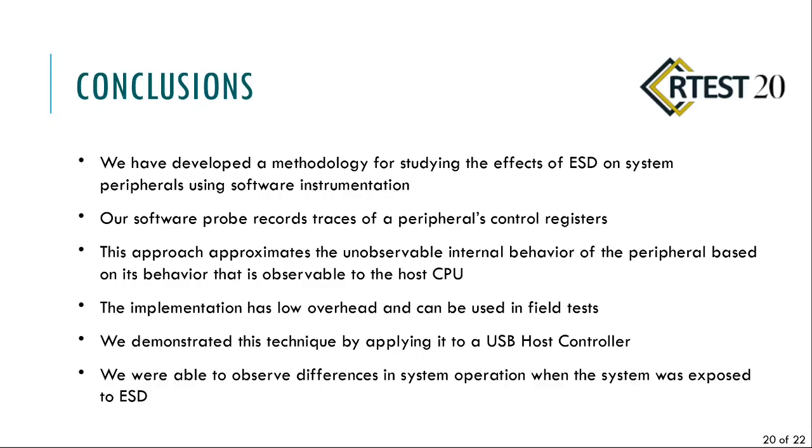So overall, we've developed a methodology for studying the effects of ESD on system peripherals using software instrumentation. This works by recording traces of the peripheral's control registers, which we use as an approximation for what the peripheral is actually doing, its internal behavior. This internal behavior is often unobservable, but we can see what the host CPU sees, and that in particular can control what happens with the software executing on the host CPU.